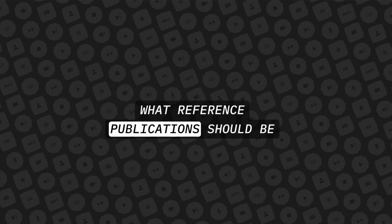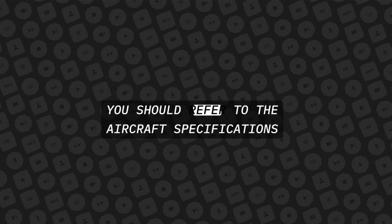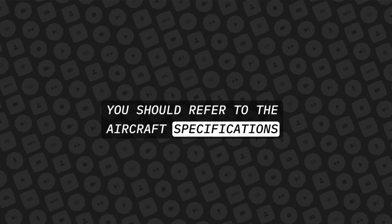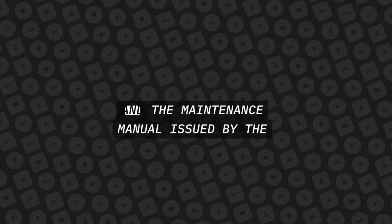What reference publications should be used to rig aircraft, including the control system? You should refer to the aircraft specifications or type certificate data sheet issued by the FAA and the maintenance manual issued by the manufacturer.